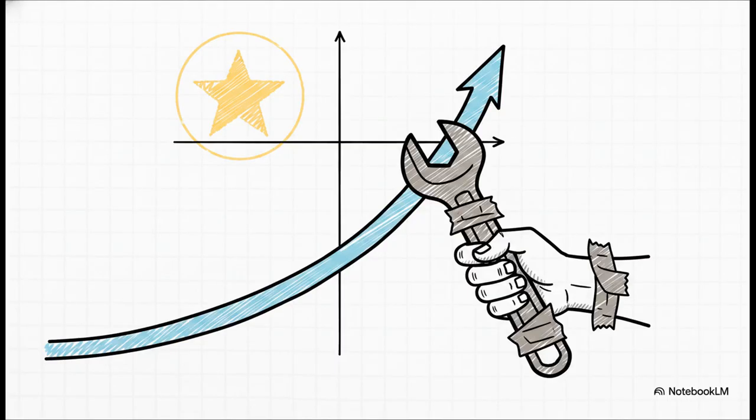Let's unpack exactly where the DMST falls short, because the overestimation of the maximum power coefficient is really just the start. It also shifts the optimum operating point to a higher tip speed ratio. Now you might be thinking, well, we can just tweak the model, right? But the results show the DMST model still fails even when corrections for tip losses are incorporated, and even when variable induction factors are applied. The underlying model just misses the reality of the physics.